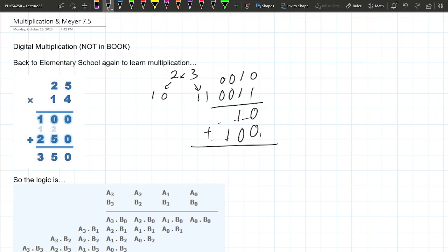Okay, so now you add these numbers together. 0 plus 0 is 0. 1 plus 1 is 1. And 0 plus 1 is 1. So now you have a 4-bit number, and hopefully this is actually 6. This is 4, this is 2, so you add these numbers together, you actually get 6. See, it works. So this we can do with the full adder, that's the full adder stuff that we already know how to do. You guys are going to build it today.